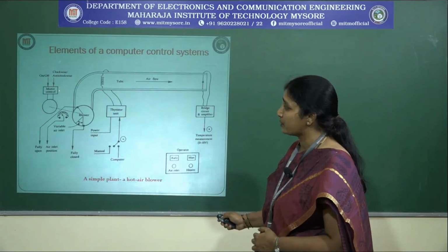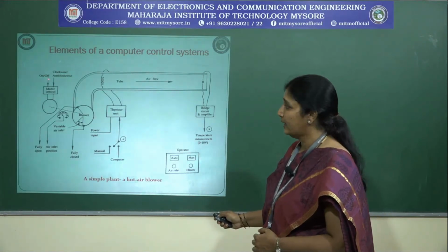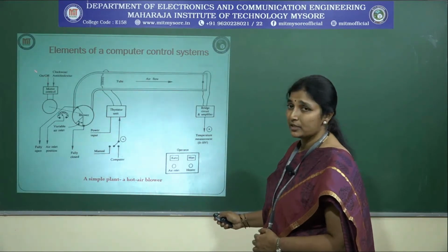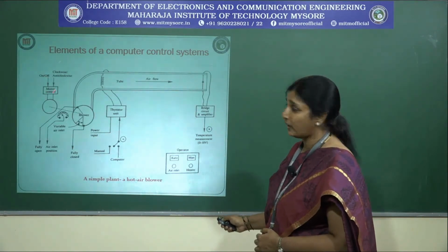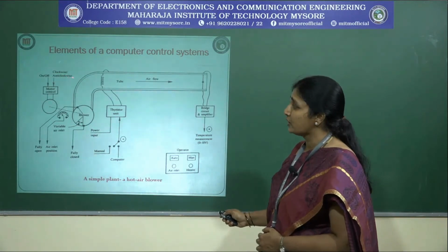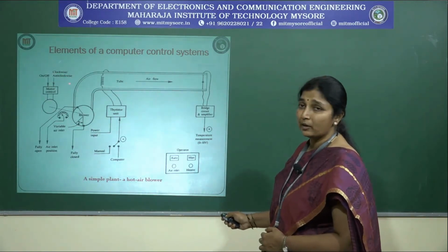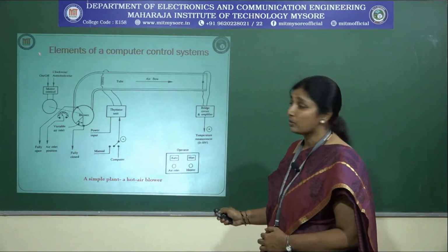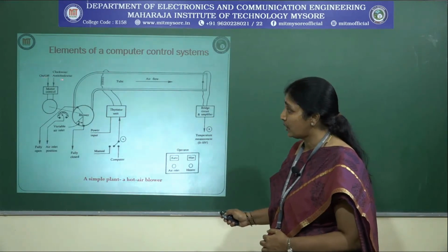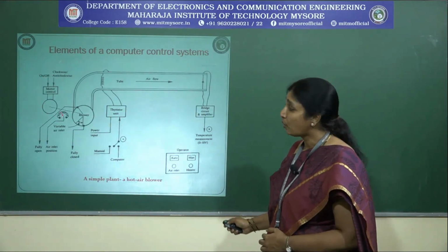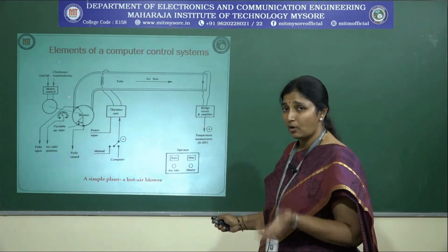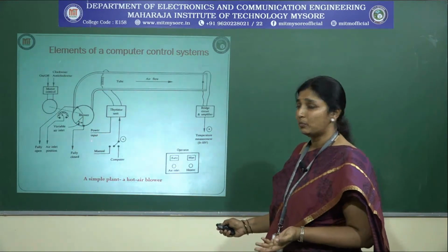These are the logical inputs. One is on, off. If you switch on logical high, then the motor will be running. If it is off, logical 0, the motor will be off. Then you have another logical expression here where you can control the movement of your motor, whether it is clockwise or anti-clockwise. So this becomes a controller. These are the two controllers given to the motor to rotate in an anti-clockwise or clockwise direction, or to switch the motor off and on.